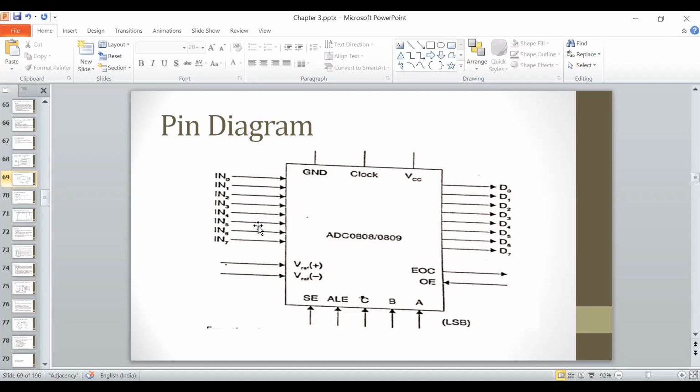ठीक है। तो इन 8 इनपुट लाइंस हमारे पास हैं, पर डेटा हमेशा एक ही इनपुट लाइन पर आएगा। किस इनपुट लाइन पर आएगा, ये डिपेंड करेगा कि आप इन 8 इनपुट लाइंस में से किसको सिलेक्ट कर रहे हो। To select this particular input line we will send one particular address on these 3 pins A, B, C. ठीक है। तो ये जो 3 पिंस हमें दिख रही हैं A, B, C, इन पर हम एक एड्रेस सेंड करेंगे और जो भी एड्रेस आएगा उसके अकॉर्डिंगली हमारी एक इनपुट लाइन सिलेक्ट होगी।